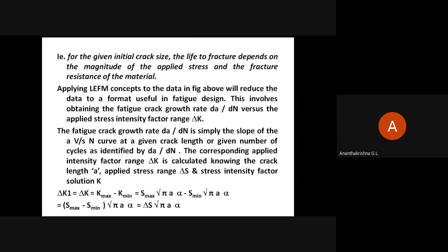That is, by applying LEFM concepts, we will be able to reduce data to a format useful in fatigue design. This involves obtaining fatigue crack growth rate data. Okay, fatigue crack growth rate is what we can get. So this is essentially delta A by delta N versus applied stress intensity factor range delta K.